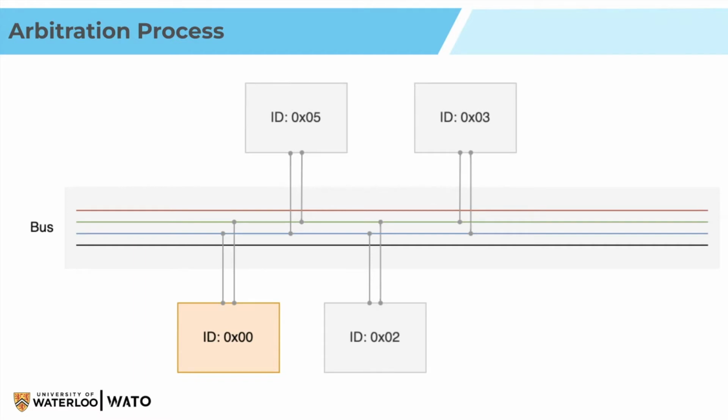So you can imagine why this is really useful for automotive systems. We can guarantee that high priority things such as your steering and your engine are able to be serviced immediately in case something goes wrong, compared to lower priority things such as your lights and horn. So this is why we have CAN, because CAN is able to support this arbitration process within its protocol.